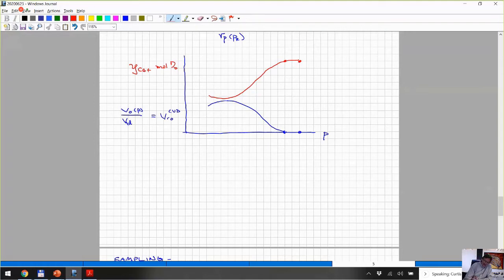But the magnitude of change here is in stock tank barrels not being sold. So you care about it a lot more than the reservoir barrels or the oil saturation that you're getting right or wrong, because this, equivalent to the oil saturation, is going to be less than the critical oil saturation anyway. And so it's not mobile, so who cares what the saturation is? That's why.